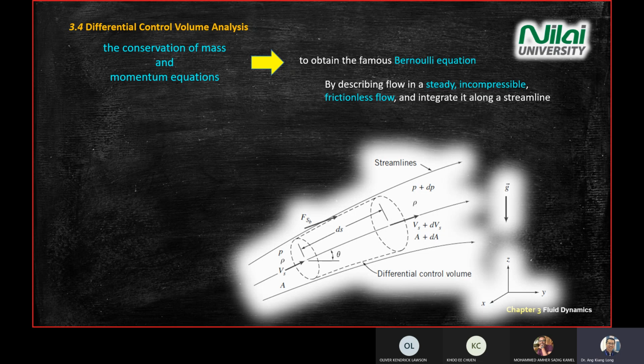So for example, I give you the area, the velocity, the pressure from the machine itself. But when you calculate for the parameter, the value sometimes will have plus minus a value there. This is because we have all these assumptions inside the equation. So when you write the report, when you see something different from the value, or you need to write the error inside your experiment, then this is one of the points.